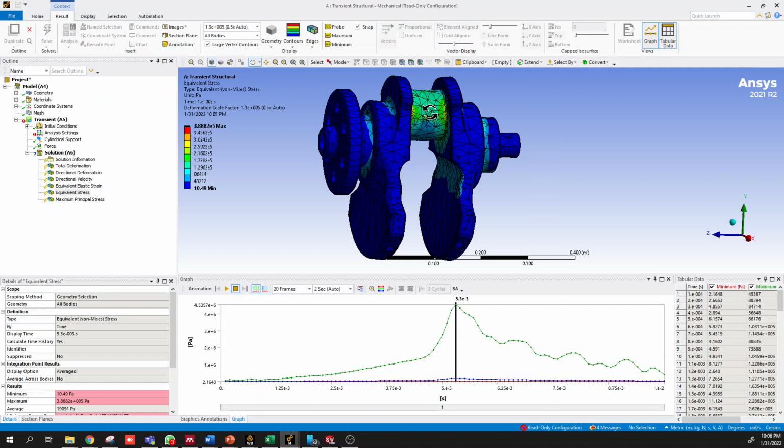I know it doesn't correspond directly to the load case, because the load case will probably be tied to a specific engine revolution rate or a specific throttle amount or torque value, but as a first guesstimate or first setup simulation, it makes sense to build the complexity up so that you understand where each setting plays a role, and when something isn't working or isn't converging, you know that there was a known quantity that worked.